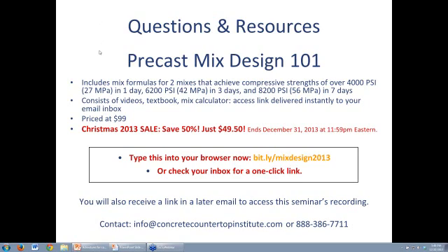So if you're using a retarder to slow down your set time, you're probably also reducing your early strength, which means you need to leave your pieces sit in the forms perhaps a day or two longer.